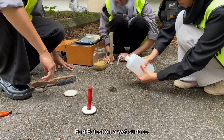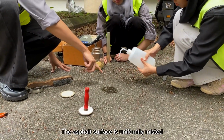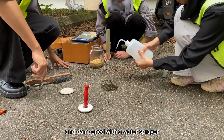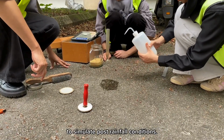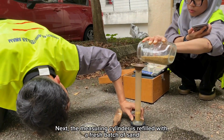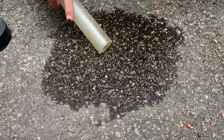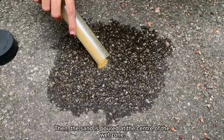Part B. Test on a wet surface. A new test area adjacent to the dry zone is selected. The asphalt surface is uniformly misted and dampened with a water sprayer to simulate post-rainfall conditions. Next, the measuring cylinder is refilled with a fresh batch of sand up to the 20 cm cube mark. Then, the sand is poured at the center of the wet zone.